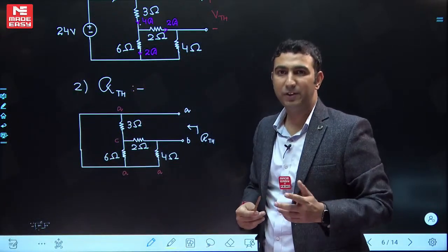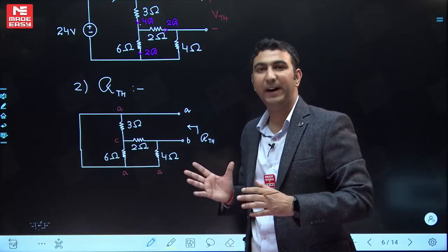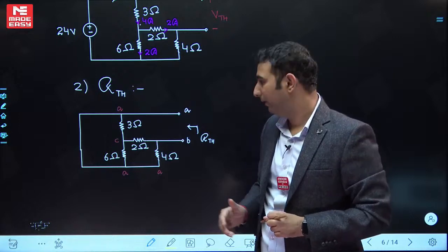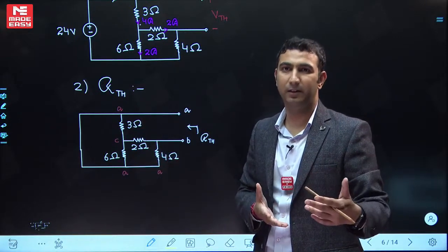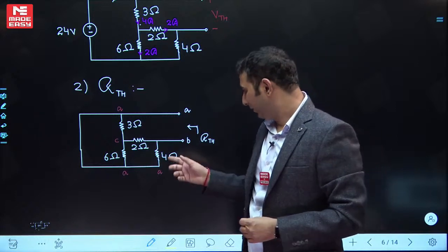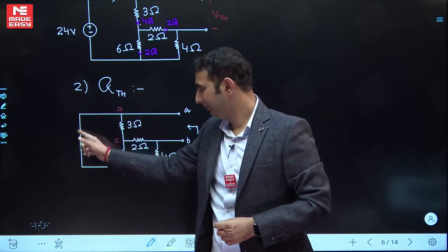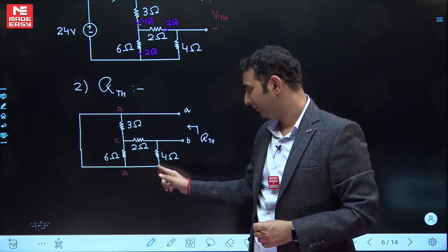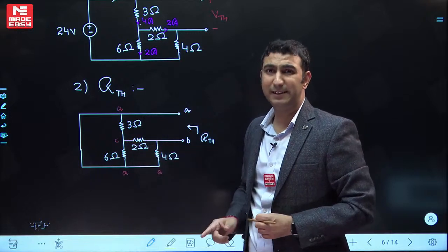Now after deactivation, whenever we have to calculate the equivalent resistance and we are unable to find it straightforward, we mark the points, because this is the basic rule that we start the equivalent resistance topic with. So if this is point A, and this is point B, this is a new point, so I have marked it as C.